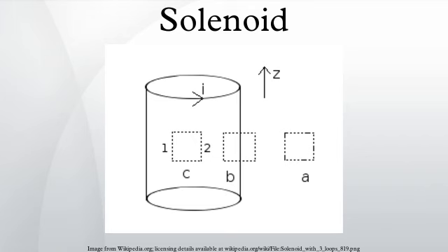Applications: Electromechanical solenoids. Electromechanical solenoids consist of an electromagnetically inductive coil, wound around a movable steel or iron slug. The coil is shaped such that the armature can be moved in and out of the center, altering the coil's inductance and thereby becoming an electromagnet. The armature is used to provide a mechanical force to some mechanism. Although typically weak over anything but very short distances, solenoids may be controlled directly by a controller circuit, and thus have very quick reaction times.